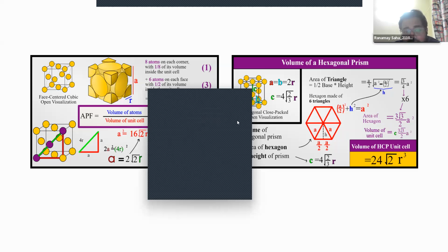One is when the liquid becomes solid, one is during the solidification, and one is after the solid has solidified and it comes down to room temperature. That is called solidification shrinkage, and that happens to be the maximum. So you have to take care of the solidification shrinkage only. So you can choose it from the options. I hope you got it.